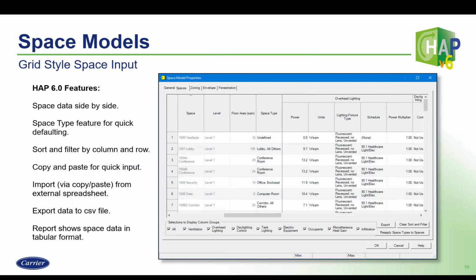A space model is the total collection of both conditioned and unconditioned spaces that comprises the whole modeled building. A space model is comprised of all the space types, zoning configuration, and assembly assignments for exterior envelope and interior construction of the entire building. For example, an office building is never comprised of 100% office spaces. There could be corridors, conference rooms, restrooms, break rooms, storage rooms, a lunchroom perhaps, or a kitchenette, and of course office spaces. Each office project will have a different mix, so will have a different space model.